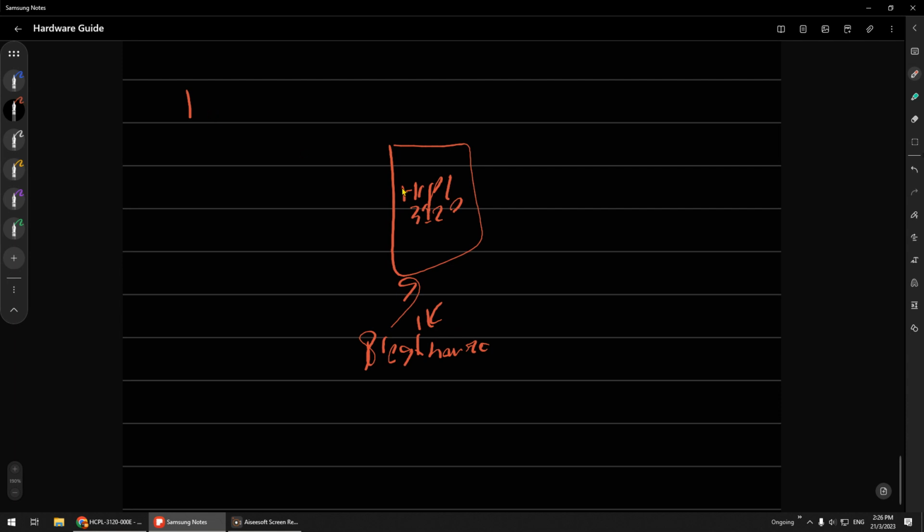Okay, and then you need to connect with the resistor here. I think it's 270 ohm. You have to buy this, and that's it. Sometimes they suggest to put some resistance around 3 ohm, 2 watt here.